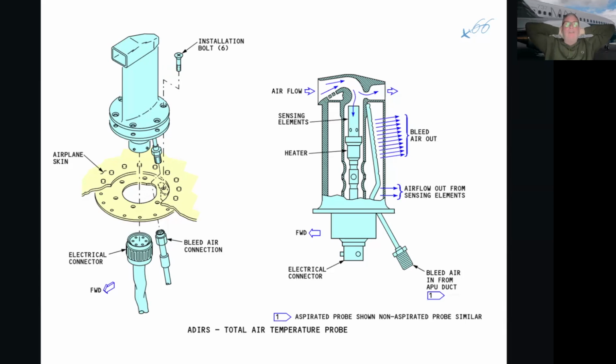We're going to see later on that the FMC's sole purpose in life is to save fuel, to calculate the most economic route from takeoff to landing, from A to B. So in order to make it the most economic flight, we have to adjust the N1, so the thrust, so that we're not overspending fuel.